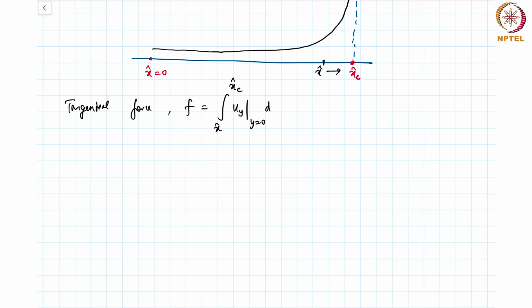along the surface, dx, and I should actually add, say, for viscosity, and this quantity simply becomes mu times, this is an improper integral here, x hat c minus, I'm approaching it from the left side, going from x hat to capital X hat. The dominant term is just 1 by h naught. This is my equation number 26. Here we have used the definition of an improper integral.